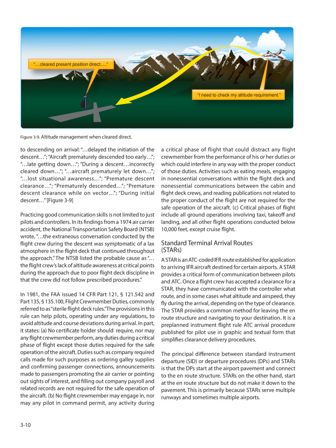In 1981, the FAA issued 14 CFR Part 121, Section 121.542 and Part 135, Section 135.100, Flight Crew Member Duties, commonly referred to as sterile flight deck rules. The provisions in this rule can help pilots, operating under any regulations, to avoid altitude and course deviations during arrival.